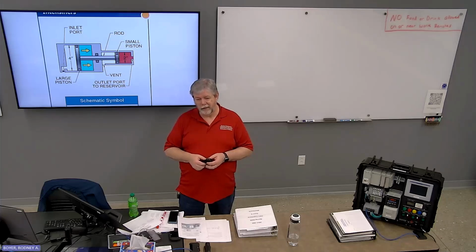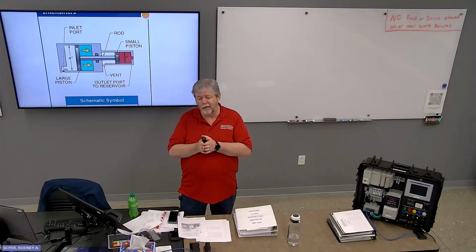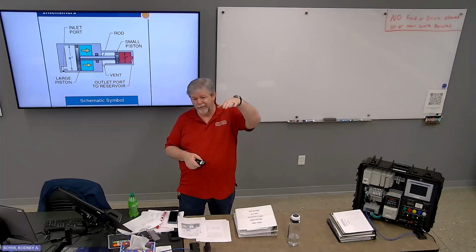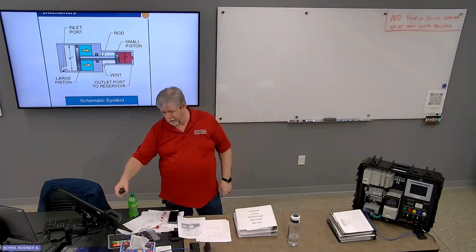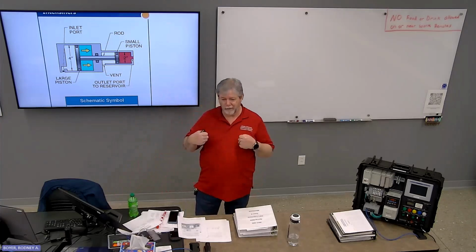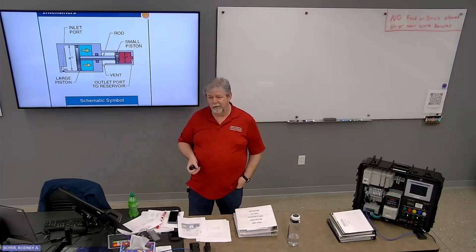But you need 7,000 pounds or whatever to lock in the press to make sure that the mold stays closed whenever you do the inject. Instead of running the whole system up to 7,000 psi, use an intensifier, and that gives you the pressure boost that you need.